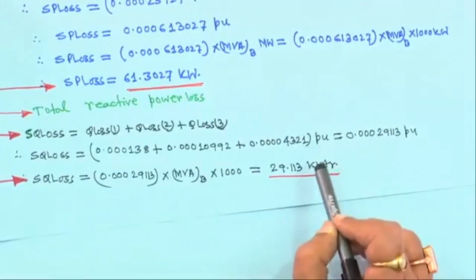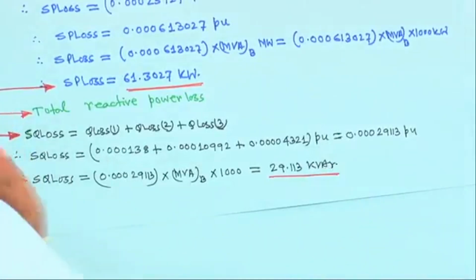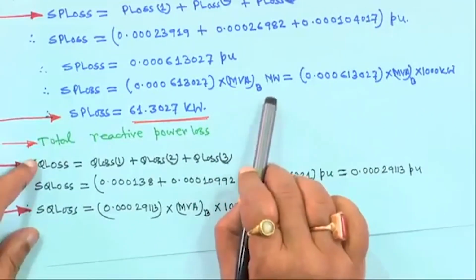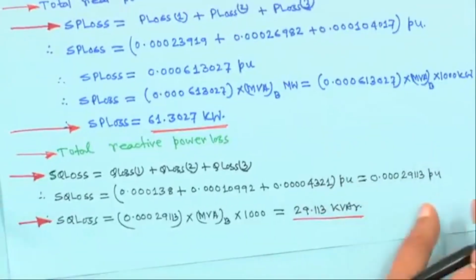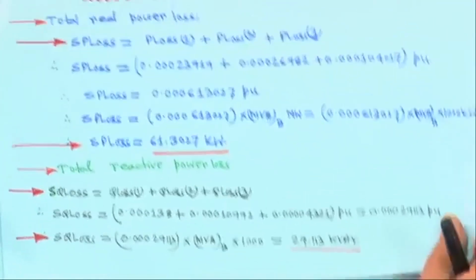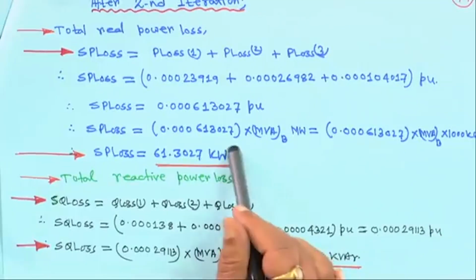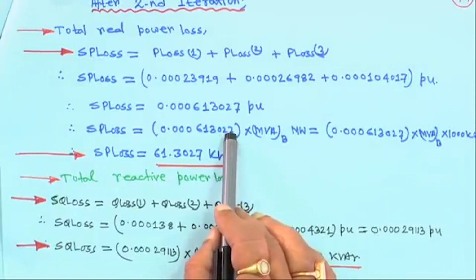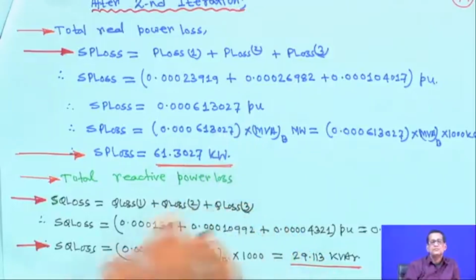If you see the voltage magnitudes of both the methods, you will find that for this example the second method is converging faster than the first one. One advantage of this second method is that throughout this computation no trigonometric term or complex number is involved. But the expression for angle delta can also be obtained using the same initial relationships, the two equations we wrote.